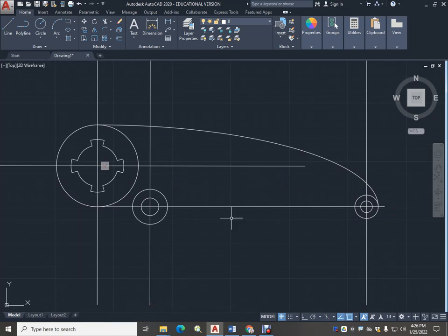Now let's do the second one. So I actually have to find the center of this. I can try to find the midpoint, but I still have these lines hanging out. What I could do though is just take a line and draw it and use the end of the line, 4.75 then, as the center point between it, and start from there.